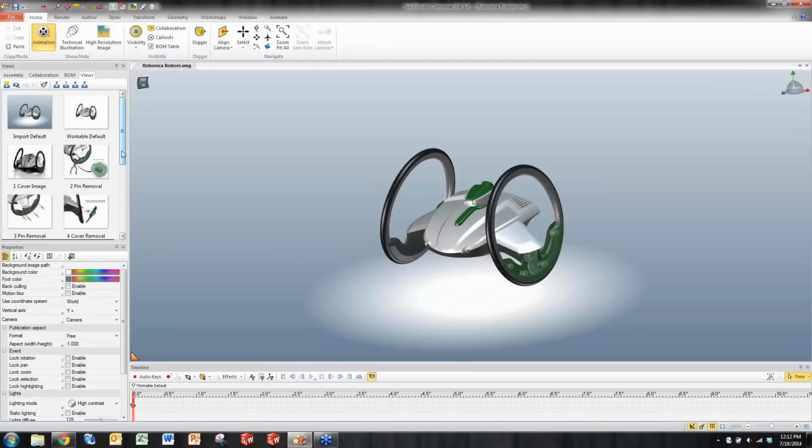So let's see here. First things first. In the timeline, we have this red bar. This represents a time bar. So wherever this red line is on any of these second markers, that's where I'm looking or viewing into the animation. This can be dragged around. So after we've created keys on our time frame that control translation of a part, or maybe opacity, something fading in and fading out as it's being assembled or disassembled, I can move this time bar back and forth within my timeline to see what's happening during the animation.